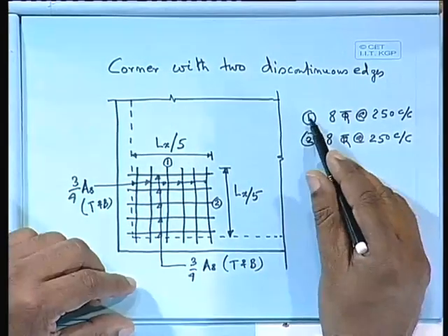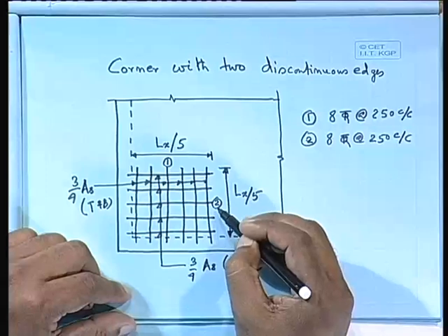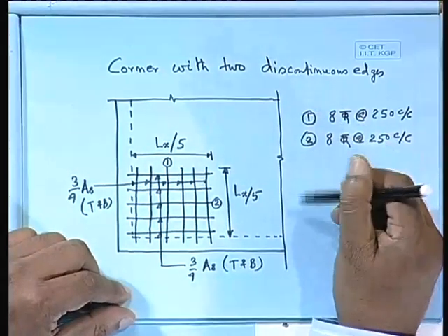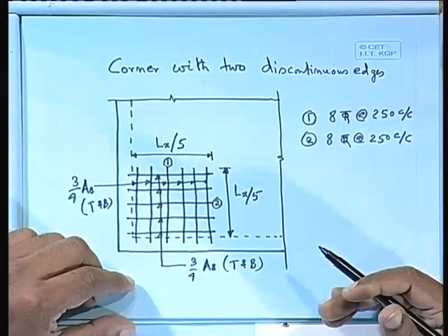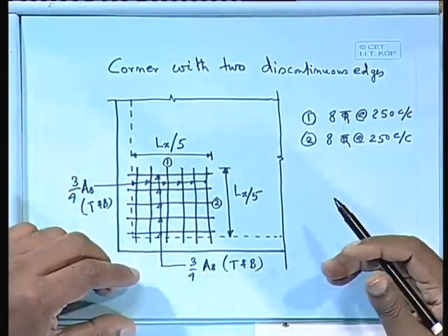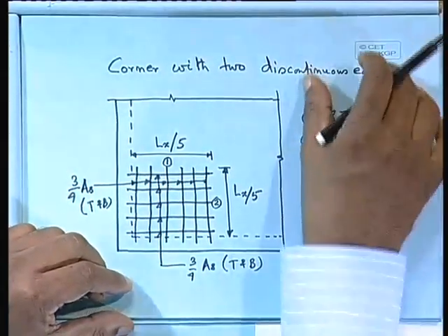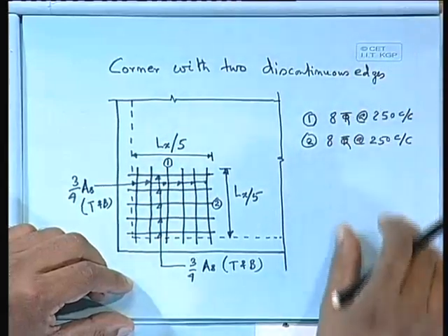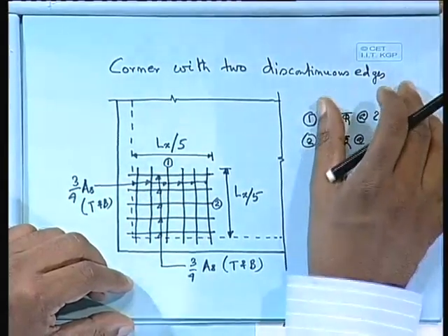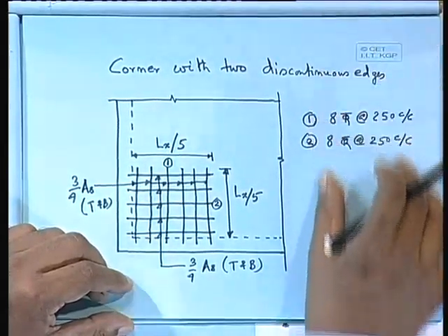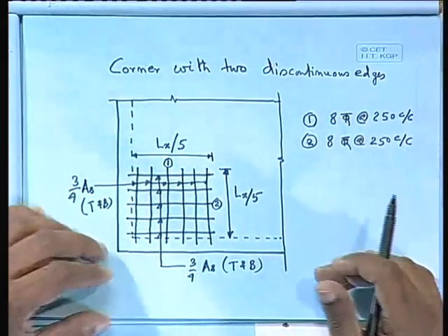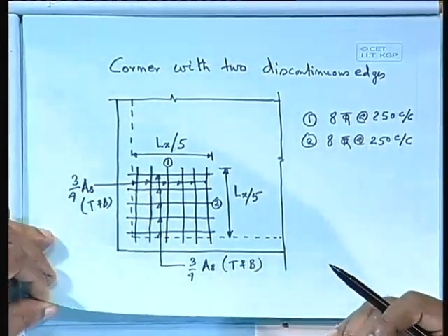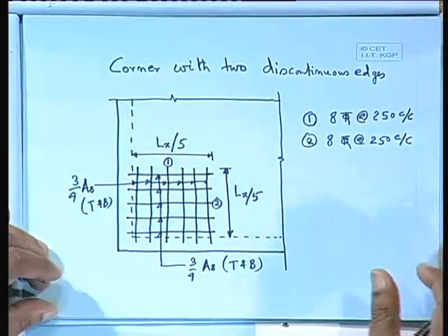That means I can simply say this is 1 as well as this is also 1. So we can reduce the number of bars. From the drawing itself they will come to know how many different types of bars you need. You have to make that list, the bar bending schedule, which you can specify separately on the right hand side of the drawing. From there they will know this many different types of bars we have to provide.